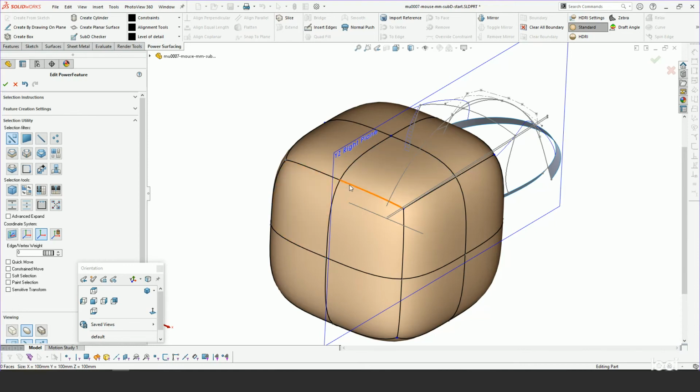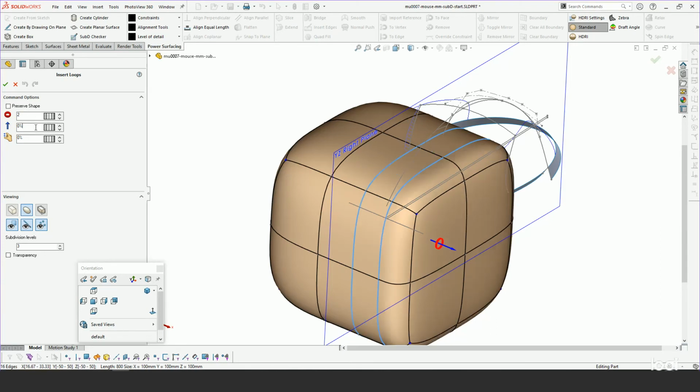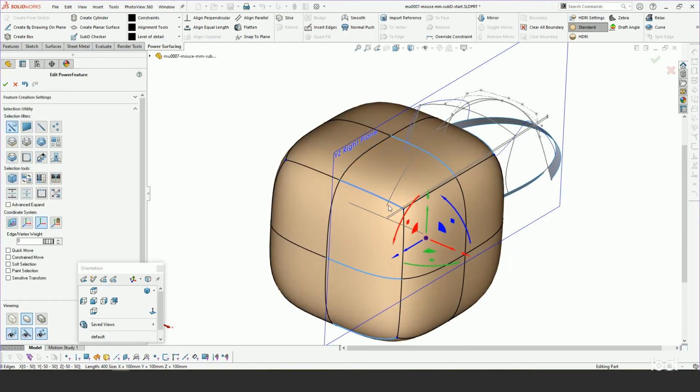So for doing loops where you're going to be splitting faces, you want to double click in the middle of the edge and then create an additional loop here, or a number of loops if you so desire. So that's one thing with selection. Also, if you want to go the opposite direction, say I want the loop to be on top, you double click towards the outside of the edge. Let's do it here down on this loop, and you can get going that direction. Remember, outside of edge, middle of edge to loop the other way.